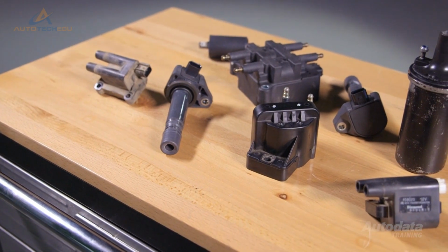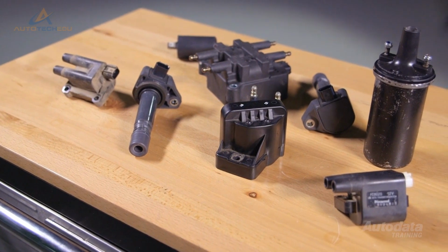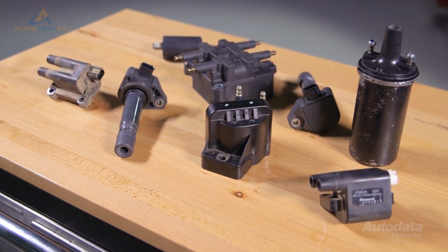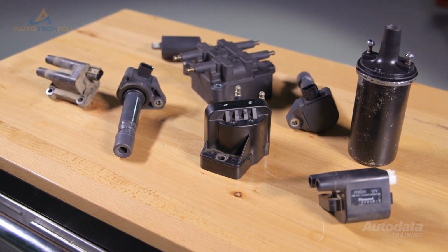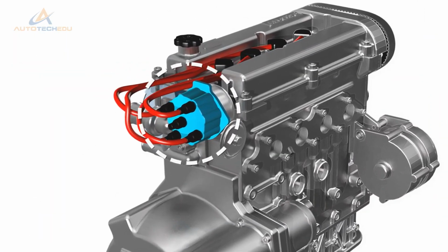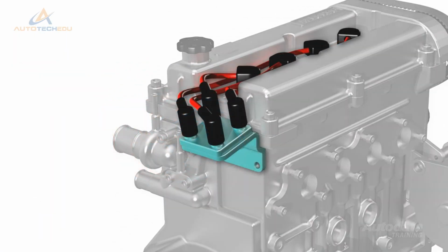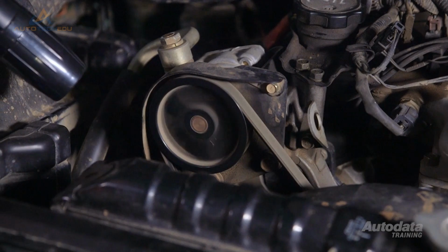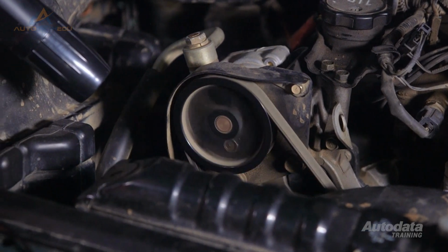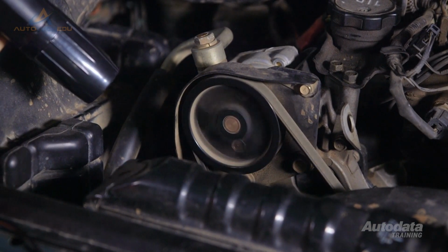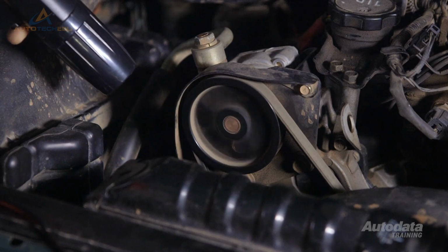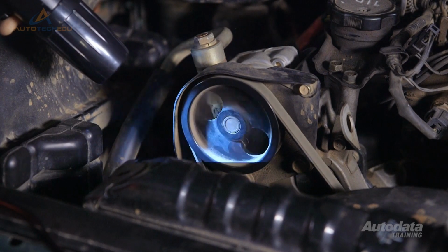The idea of introducing more than one ignition coil to an engine is very clever, as it has several key benefits, such as the elimination of the distributor and any moving parts associated with it. This helps enhance the overall reliability of the ignition system. Also, we now have electronic control over spark timing advance and have eliminated mechanical adjustments to static timing.